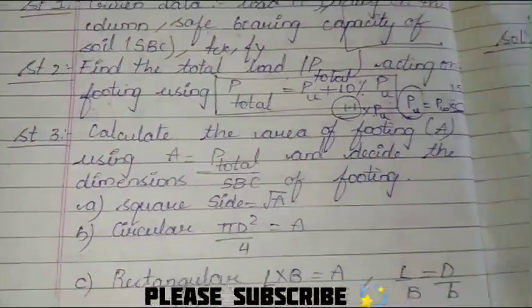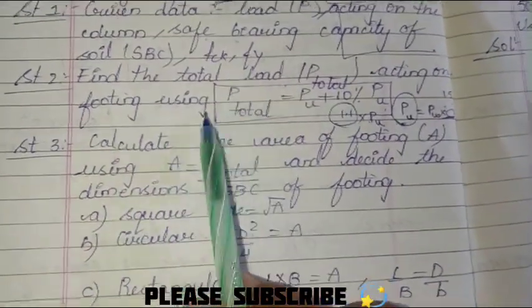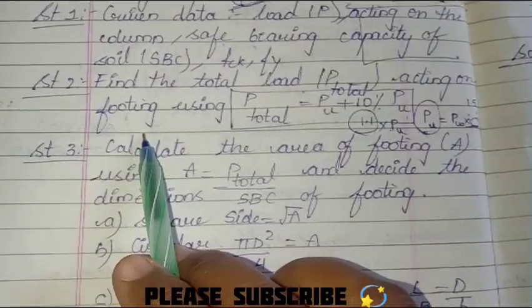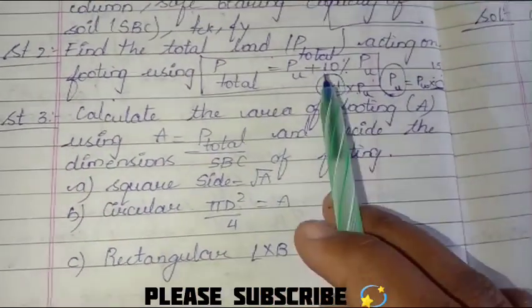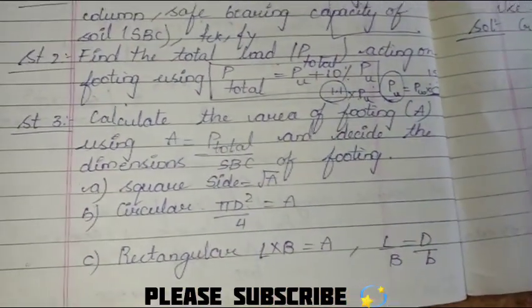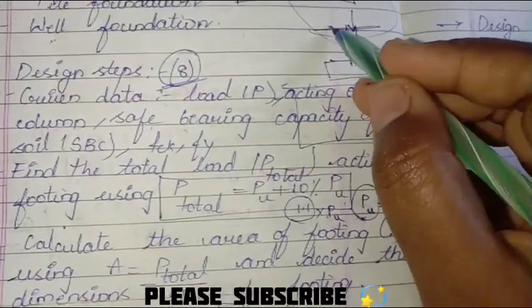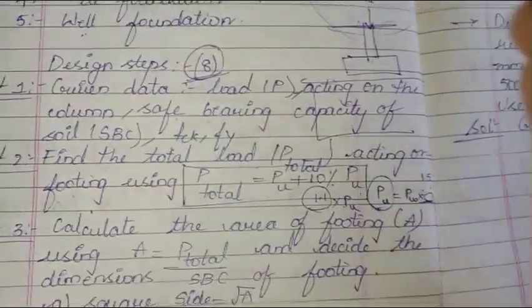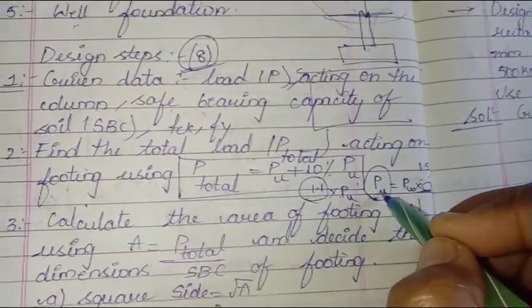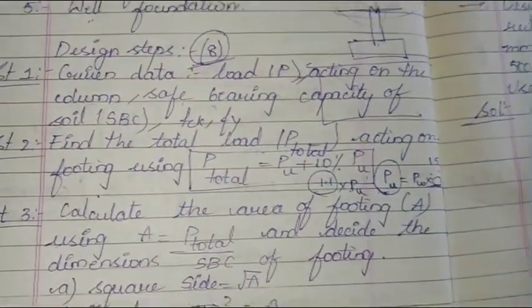Okay, the first step is writing the given data. The second step involves finding the total load acting on the footing. Next, calculate the area of the footing. Generally we are not considering the adjacent loads that are acting, we are neglecting them. In that case we'll be considering the ultimate load, and also this extra load, that is 10% of the ultimate load.